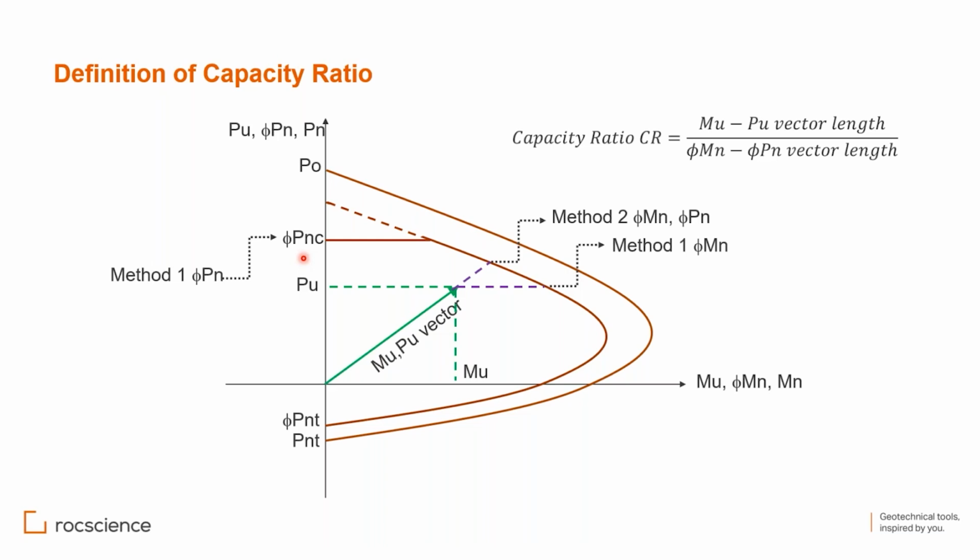So we use the tied columns, not the spiral, because if you use a spiral, you need a lot of spiral reinforcement, which is not applicable in piles. It will be very close spacing for large diameter piles, and the concrete will not flow properly. That's why most piles have limits for the minimum spacing. It's different than the design of columns.